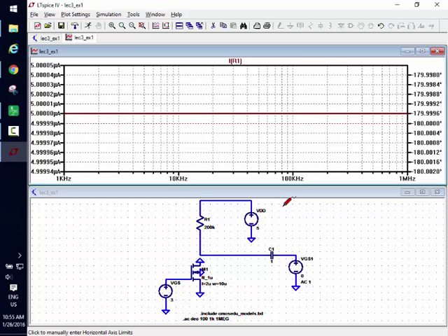Is it making sense? Okay, so now I know whatever the resistance is down here will be in parallel with this 200K because this resistance is connected to AC ground. The resistance down here through the MOSFET is connected to AC ground, so the two resistors will be in parallel. Does everybody see that? Questions? Let's go ahead and save this so it pops up when you sim.